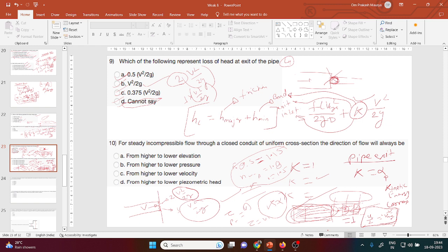As engineers, we focus on keeping the entire system safe, not only a small part. If you design using the lower velocity, the system may look stable, but it may fail. Because this is a long pipe, for the whole system to be stable, we need to consider the maximum one. So I think, Francis, you got the reason behind it.